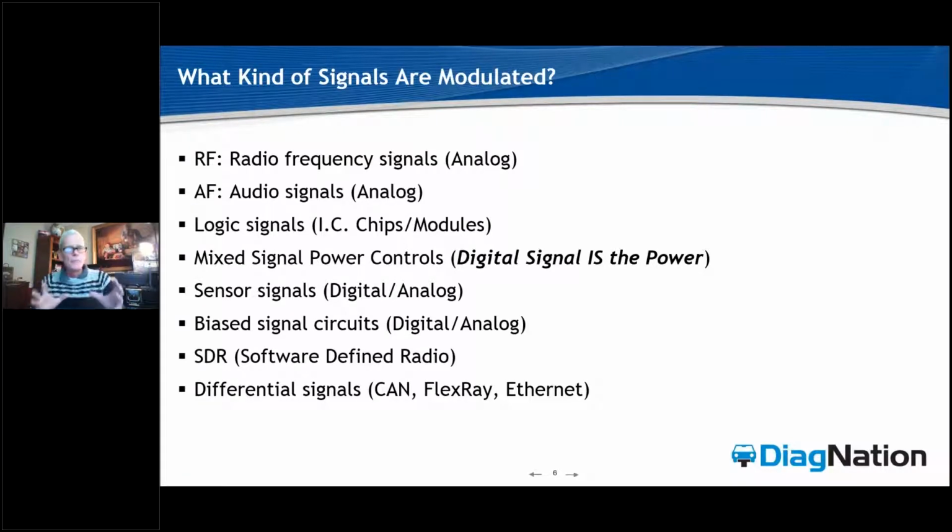See, this is where we depart from 12-volt DC electronics. And in systems such as the ones we're going to cover today in the fuel pump area and the, say, Valvetronic motor area on, say, a BMW, these are where technicians can get in trouble because they're expecting DC grounded operation, and what they're seeing is AC frequency waves controlling that system. Really, really different than what we're used to in our industry.